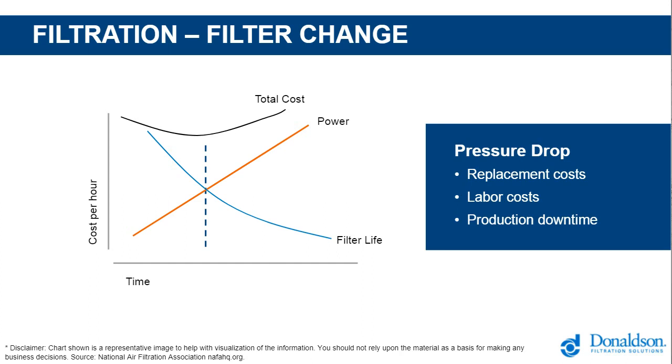Regardless of whether these filtration elements are filter cartridges, bags, or panels, when you go really beyond that point, you're going to introduce high risk, higher operation costs, more usage of electrical power, more usage of compressed air. Your pressure drop will increase, and you should really think about the higher replacement costs, the higher labor costs, possibly longer production downtime, and so on.